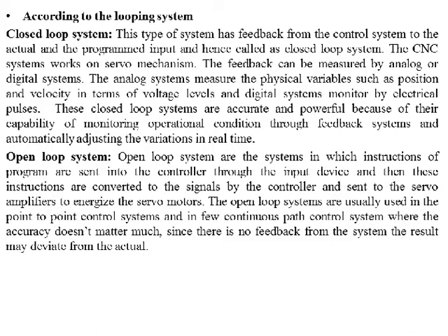Here the drawback of this type of system is that the accuracy is less. So where we do not want the parts to be produced to much accuracy, such type of systems can be used. So the major drawback of open loop system is that the accuracy will be lacking, and because of the absence of the feedback element, there is a chance of deviating from the actual position of the job or the actual type of the job required. So the result may be violated.